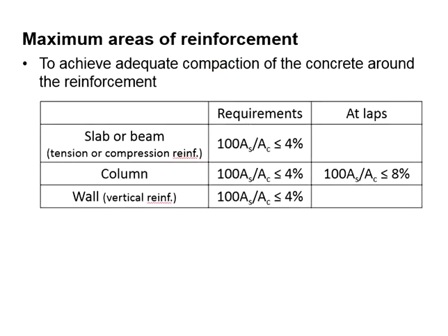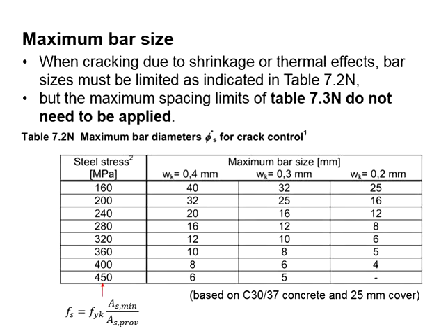As for the maximum bar area, the requirement for the slab would be the same as the beam, which is not exceeding 4% of the cross-sectional area of the member. Most likely the maximum bar area will not be exceeded. The chances of this coming out for the slab design will be quite slim as far as the final exam is concerned.